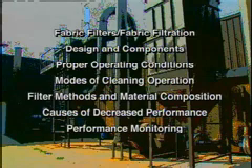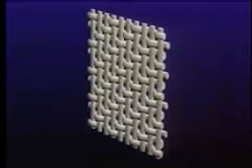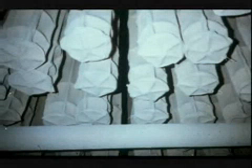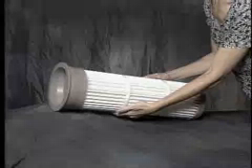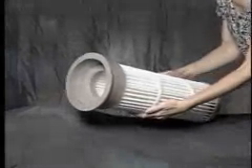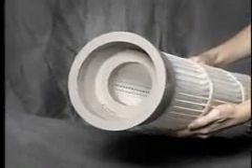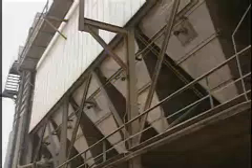Performance monitoring. In filtration processes, particles are removed from the contaminated gas stream by depositing them on filter material. The filter is usually in the form of cylindrical fabric bags, hence the names fabric filter or baghouse, but it may be in the form of cartridges that are constructed of fabric, sintered metal, or porous ceramic. In general, fabric filters are capable of collection efficiencies greater than 99%.